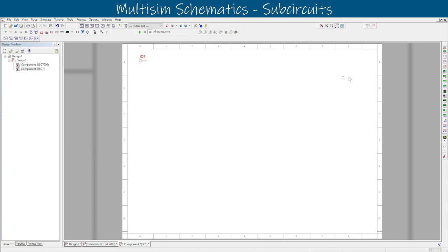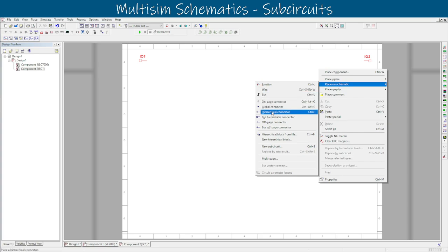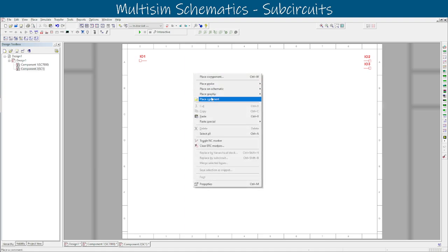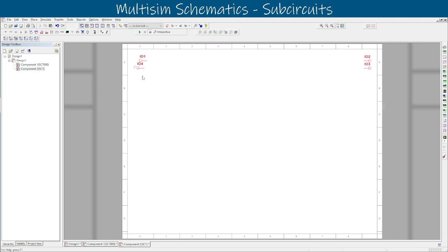And I like to Control R this before I drop it, just in case it tries to place on the wrong side. Because if you drop it just as a normal pin, it'll stack it over here, and then if you try and rotate it, it won't actually move it to the other side. So when you go to place a pin and put it on this side, get a new pin and rotate it while it's in the air. Control R until you get it to the spot you want it. And then you can place it down. Right? Otherwise, it'll try and just put it on the side with the other pin. But that is how we do that, right?